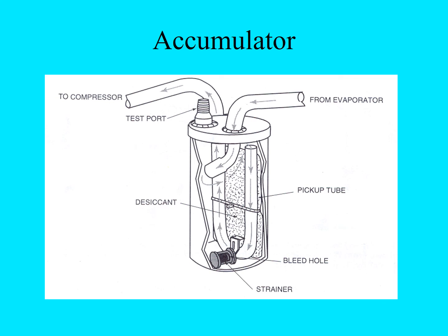So this is the layout of an accumulator, and from the evaporator we would have vapor coming into the accumulator at the top. And again, if any liquid refrigerant, low pressure, low temperature liquid refrigerant, made it to the accumulator, it gives it a chance to basically drop to the bottom. So you could end up with a little liquid down here, and then it would vaporize.